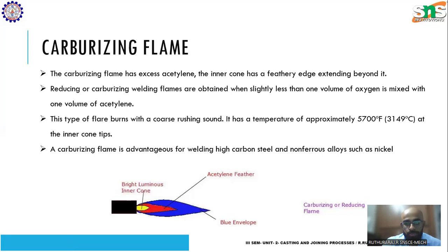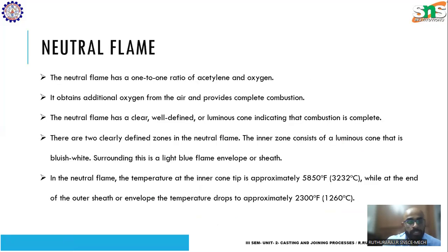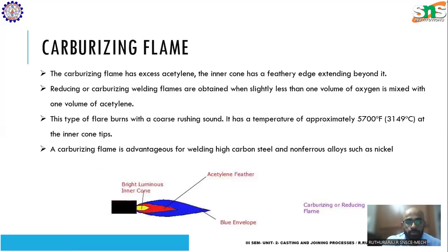See the temperature generated. It is around 3150 degrees Celsius. But if you take a neutral flame, the temperature generated there is 3200 degrees Celsius. So the carburizing flame is slightly lower than the neutral flame.